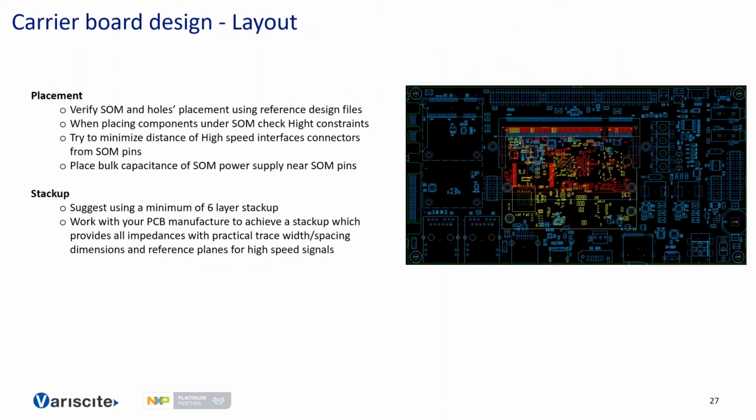In terms of placement, the layout and schematics design files are provided on our FTP. So you can use them for symbol use, placement, and footprints. It can save you a lot of time. When you come to place the SOM and its holes on your carrier board, you can either import the layout to your layout file, or use the DXF provided on our website and import it to your layout.